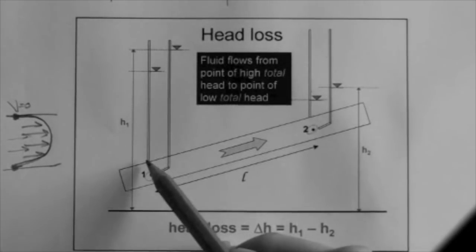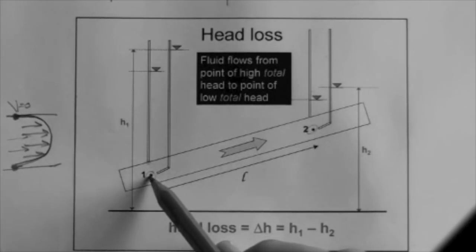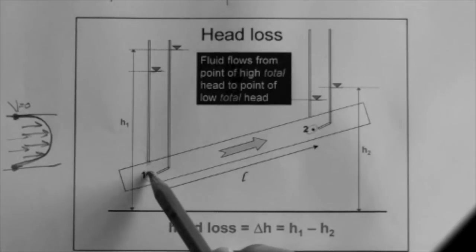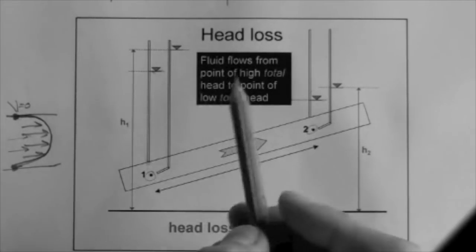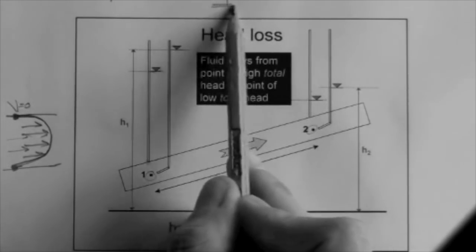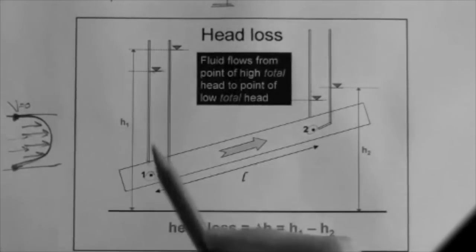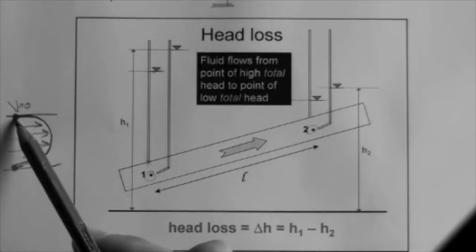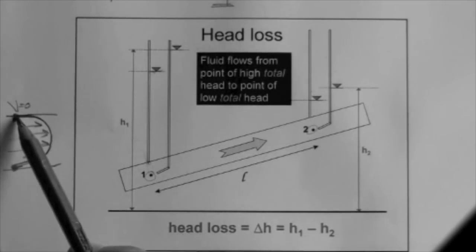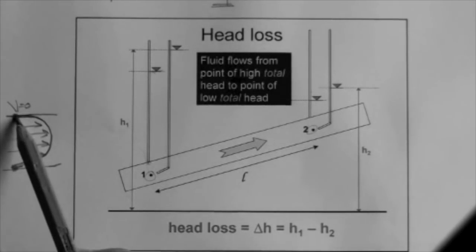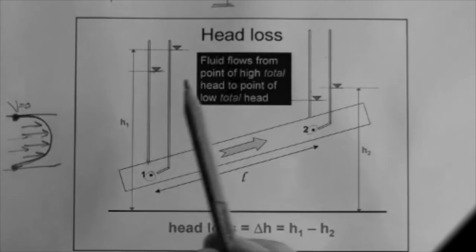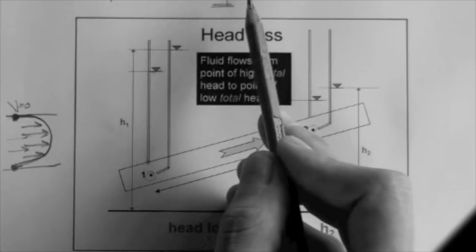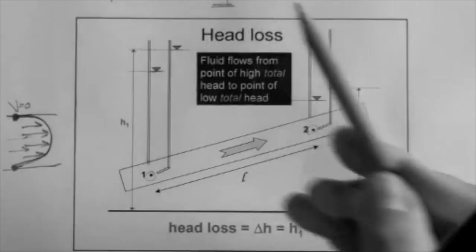So the level of water from this point all the way to here, that is the distance the water rises, is associated to the pressure head, because the fluid here in this boundary is under pressure, it's pressurized, but it is not moving because the velocity is 0. So the piezometer, this one, captures the pressure head and not the velocity head.